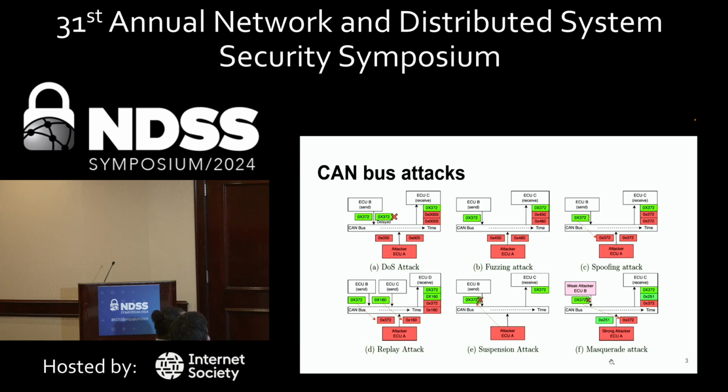Next, replay attacks resend previously valid frames at different times. For example, recorded speedometer values could be replayed at a later time. All of these injection attacks introduce additional frames into the CAN bus. However, suspension and masquerade attacks do not introduce additional frames during the attack period.